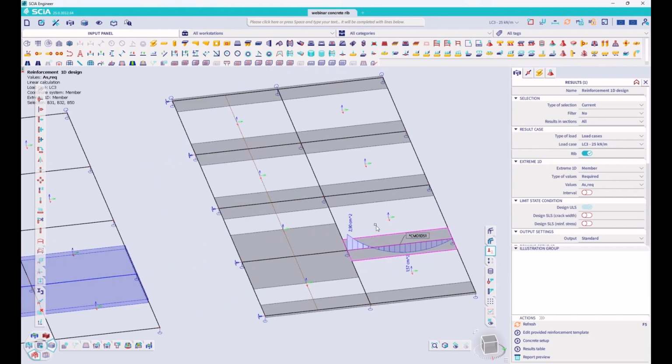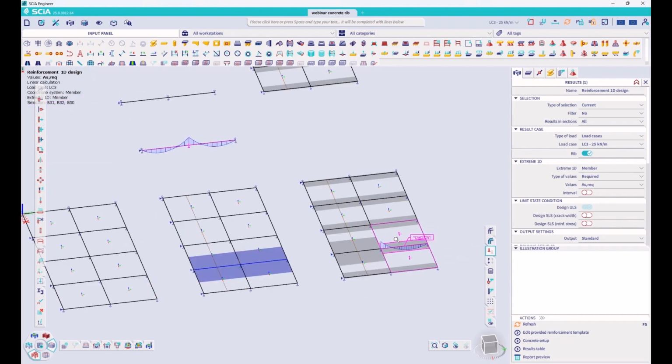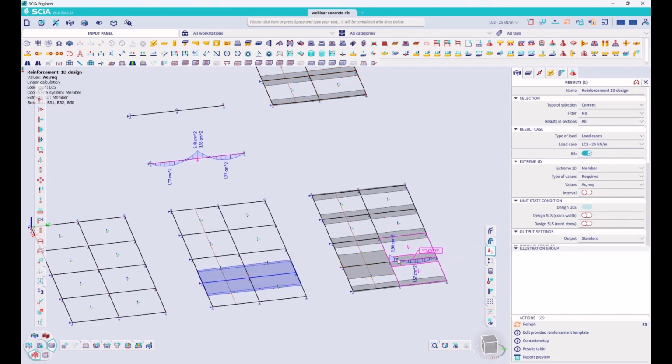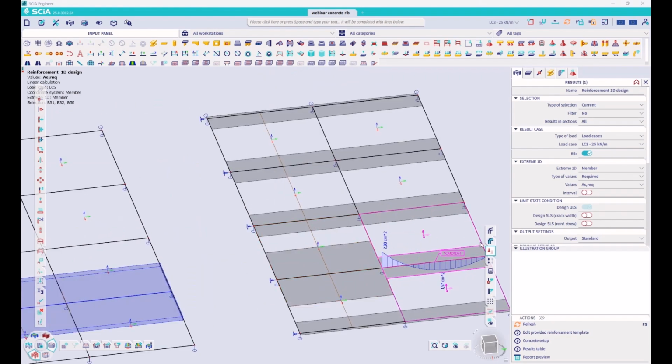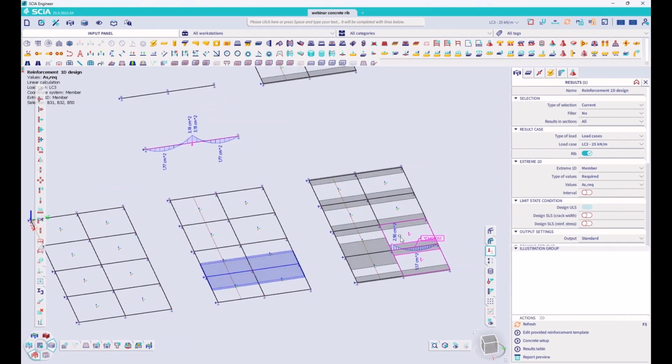But this also means that I'll need to reinforce the plate in this model, or with this rib, more compared to the plates in the other models, because the forces that remain in that plate need to be taken up as well, and we'll need to do that by reinforcing the plate a little bit more.